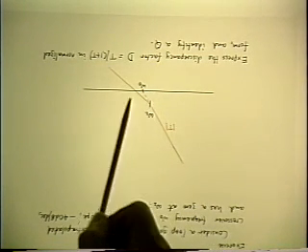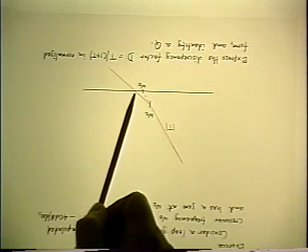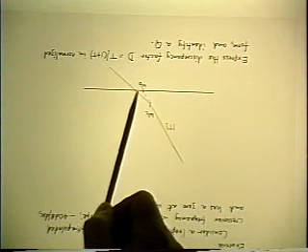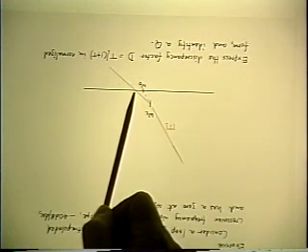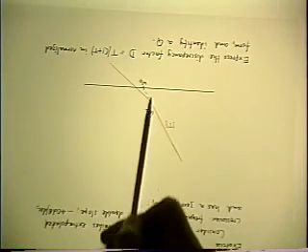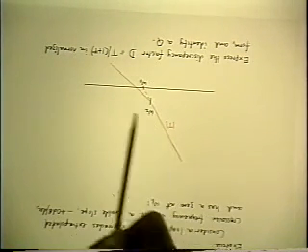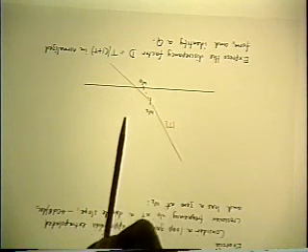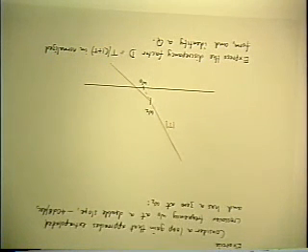Because in this problem, the omega 0 was defined as this point. And in the second problem, we used a different position for reference. So that's why the formula was different, but the answer for the relationship between phase margin and Q is the same, because it had better be the same. So that's one of the things you feel a lot better about once you see the reason why.